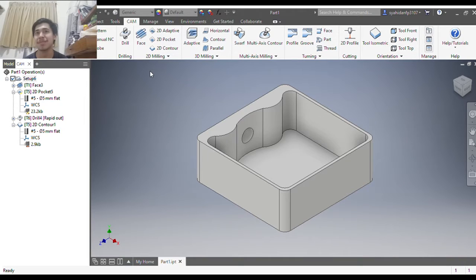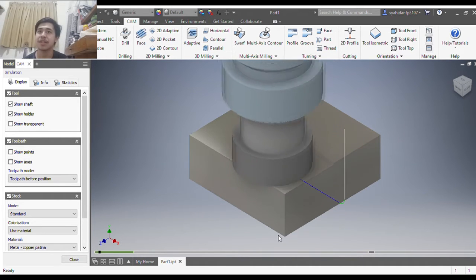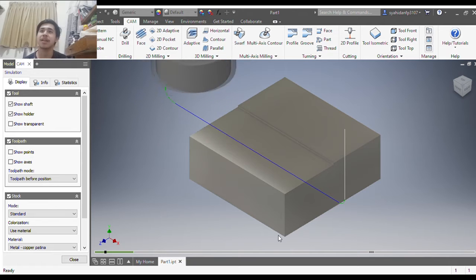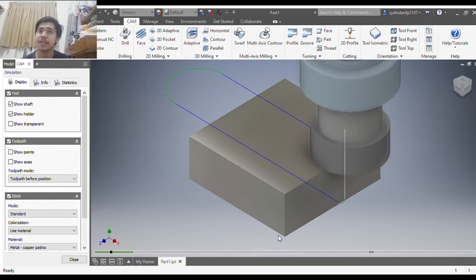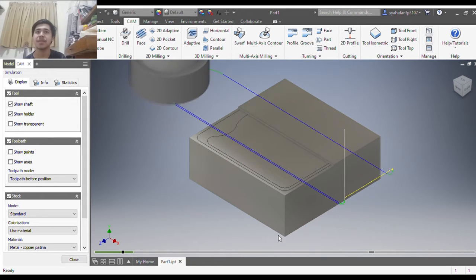Okay, now we're talking about machine processing. We got the first part. In the first part we use the milling machine, and the first step is face mill with a 15 mm face tool, with a 6-minute setup time and 169 seconds of run time.